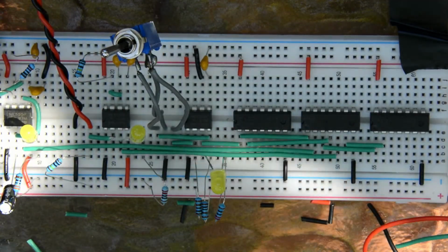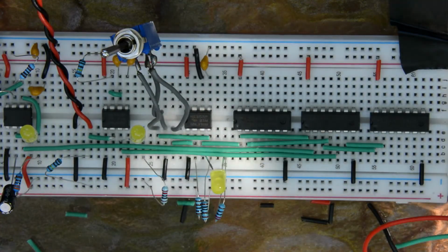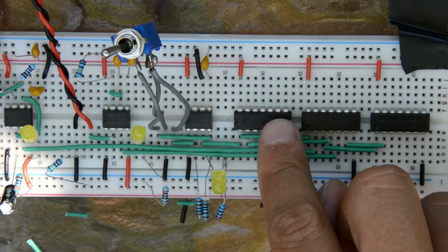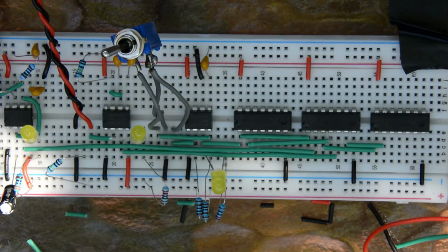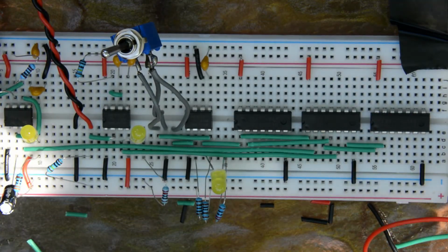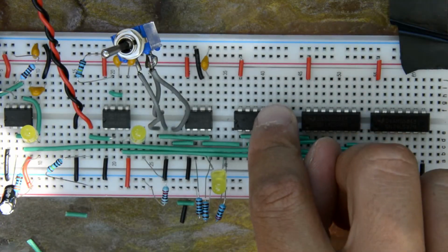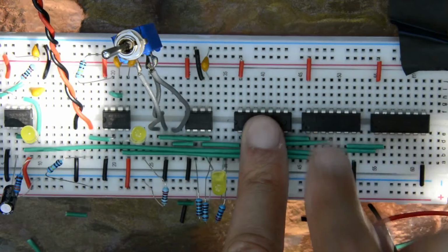Okay, and then halt is an active low. Okay, good. So now we're going to use, so wait, but actually we need to look at the pin out for this 04. So pin 8 is an output here. So we're going to just invert that. Okay. All right.